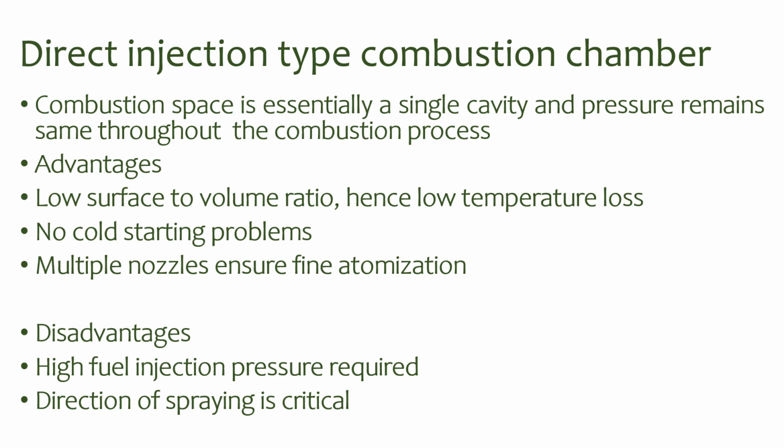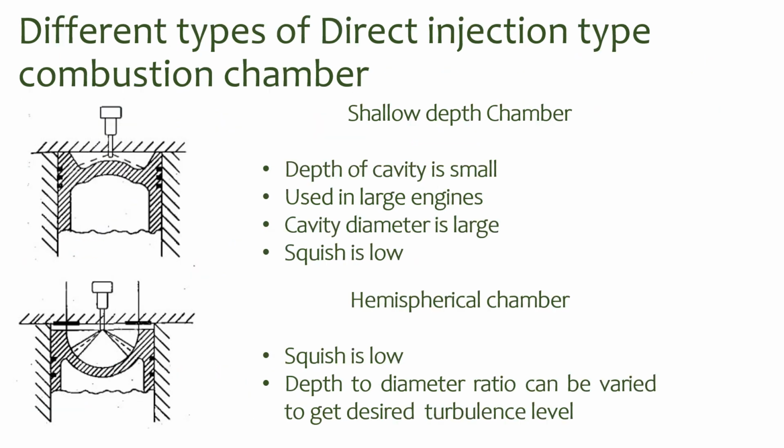The disadvantages are high fuel injection pressure is required, then direction of spraying is very critical. Now we'll see different types of direct injection type combustion chamber.